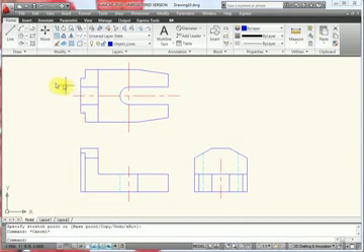So to draw a multi-view drawing, you make a lot of construction lines that are offset from each other, basically a grid that is customized to these different sizes. And you basically start with a boxed area with a bunch of lines through it, and we'll switch layers to an object layer so we can organize between our construction lines and our object lines. That way later we can turn off our construction layer. And we're just going to start connecting the dots between the intersections of construction lines. So I'll now open a new file and start that.